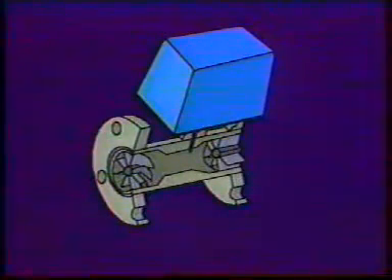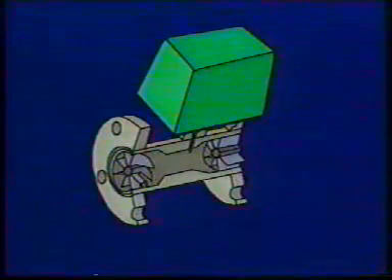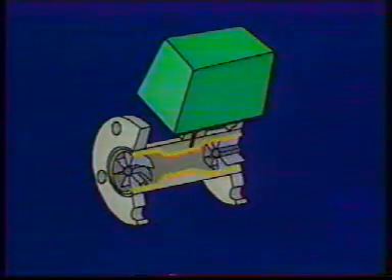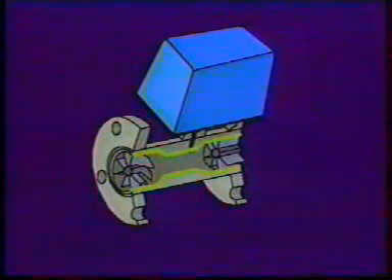Another type of vortex detecting and measuring instrument is the vortex precession flow meter. In this type of flow meter, the fluid is forced into a swirl condition by guide vanes that are sometimes called swirl blades. As the fluid exits the swirl blades, it is contracted and then expanded in a venturi-like passage. The center of the swirl becomes displaced from the meter center line.